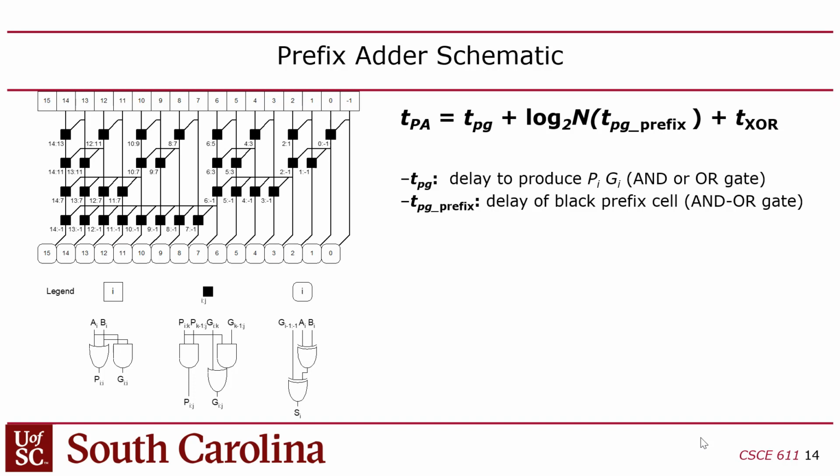Right? So you can join these groups together arbitrarily, and ultimately your goal is to get each bit down to -1, right? And these are the carry in. So if this is a 16-bit adder, the 15th full adder will have a carry in that will be the generate that's 14 down to -1. You guys with me? Now, once you get down to this bottom level, you don't care about propagate, but you do need propagate for all these other black blocks.